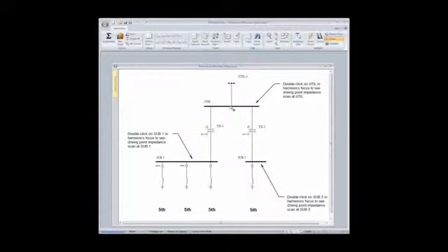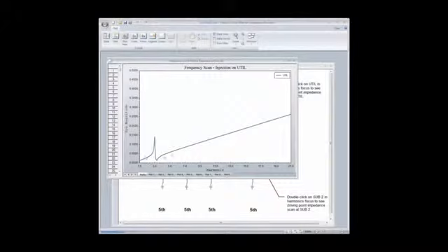So a key item in notch harmonic filter application is going to be buffering. And here we have a clear, good reason that we can apply a filter down on this location. We may have, for instance, a load down here that we want to reduce the distortion going out through the transformer. In that case, we have this buffering impedance. And if we do a driving point impedance scan, truly, we do see the effect of the filter is minimized. And on top of it, where it's tuned and it resonates, those points are being shifted.